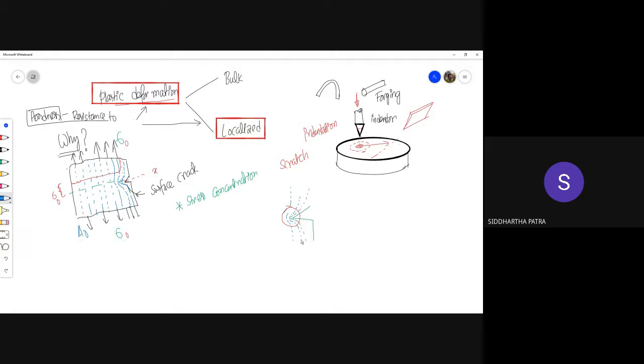Now imagine you are far from the crack tip. This much region is carrying, let's say, 1, 2, 3, 4 parts of that 100th of A0 times sigma 0. And all of that has been concentrated near the crack tip into this tiny region. Because of that, the stress, the force per unit area, skyrockets at the crack tip. That is the theoretical prediction using the elastic model, assuming the material to be perfectly elastic.